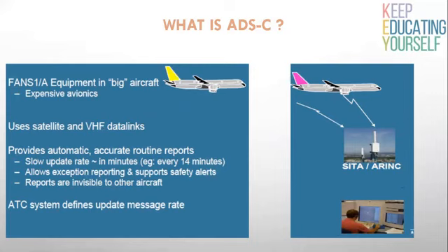For example, the ground system may demand reports when the aircraft reaches top of climb, at position report points or other navigational waypoints, or at specified time intervals. These reports basically replace verbal reports from the pilot and facilitate the application of procedural separation. Please view our video lecture on ACARS.